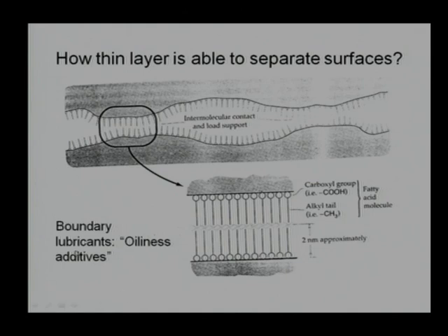That is why many times we call this kind of additives or this kind of lubricants as oiliness additives. They have oiliness property, which is they have attachment property. It cannot be easily separated. It requires some force, some push force to separate the oil from the surface.